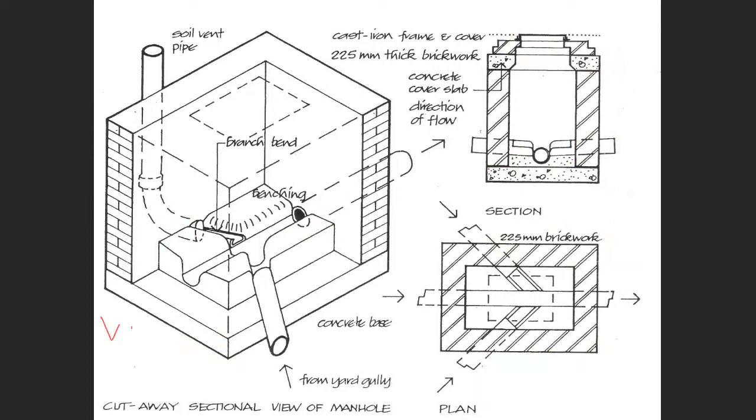V.6.5. You can refer to your SMM. Number one, you can see the word channel. So channel here is referring to the pipe work. Okay, so the pipe work is number one. You have to measure in number. This is in contrast with the pipe work in your trench excavation, in your underground pipe. This is only the pipe inside the manhole. Remember, pipe inside the manhole must be measured in number only.